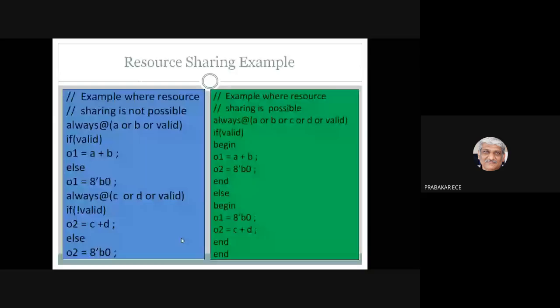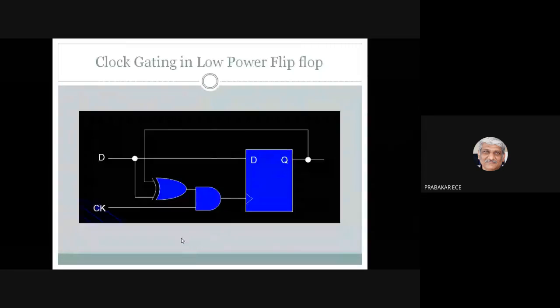So this is actually one such example of resource sharing. The same adder will be used for both the cases, right? So here actually I have written two adders, but if you write it in a valid case statement, right? If you are in a statement where I can check both the statements, only one adder will be there, so that instead of two adders, I can have only one adder here.